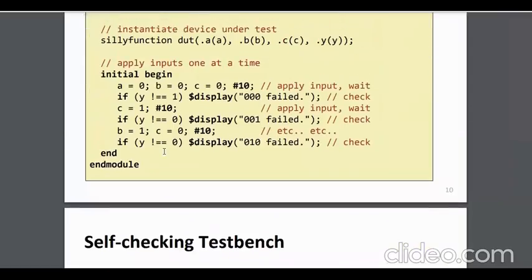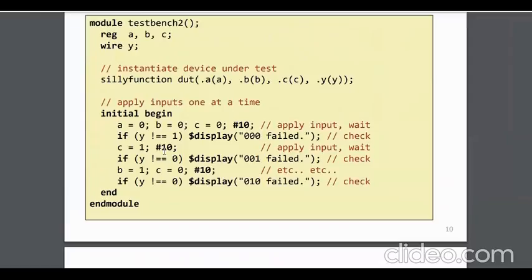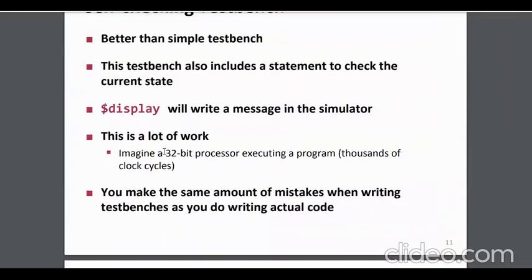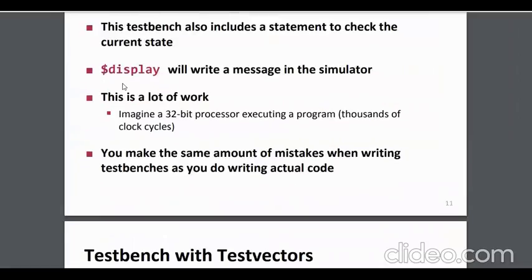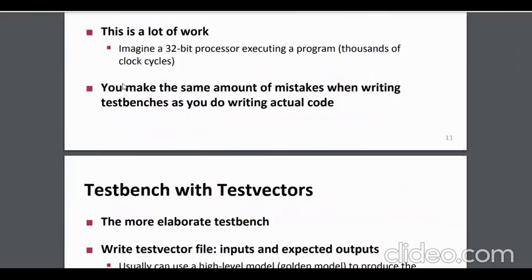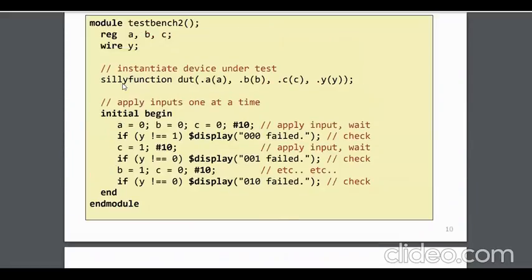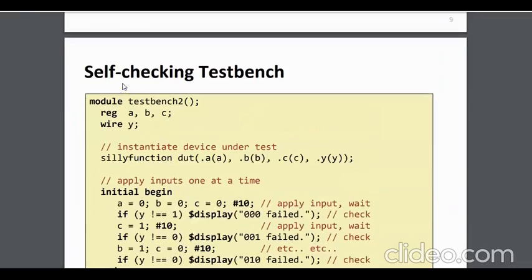Okay, this will be a linear test bench. This is also known as a linear test bench or simple test bench. Then you will be having $display to display the values of A and B. If you want, you can have $display, $strobe, $monitor, anything. Okay, and that's it. So now you've got some idea what a test bench is and how I can write my test bench.